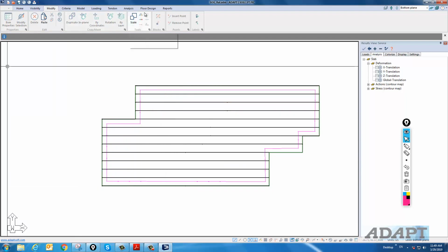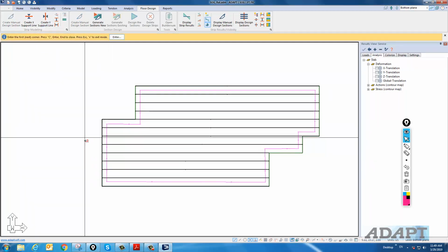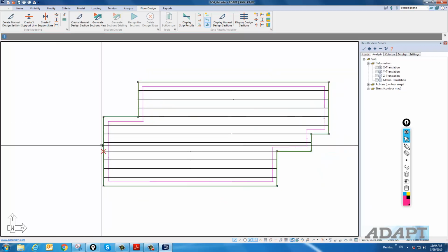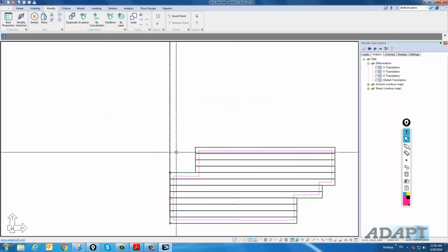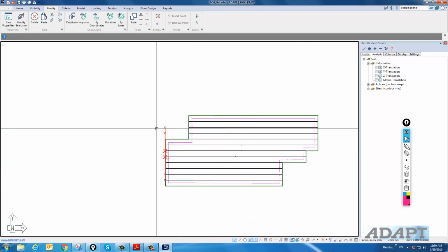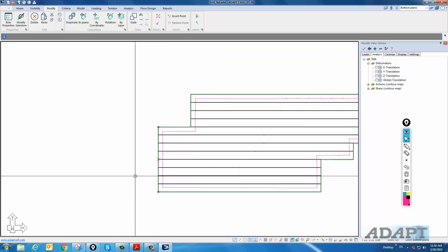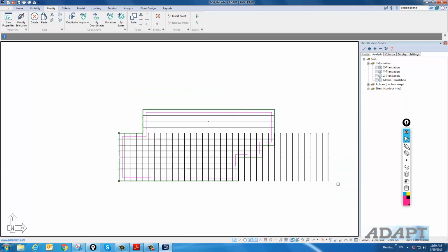Now I'll do the Y support lines. So back under floor design, I'll create this support line, and I'm going to copy that support line. This will be every 5 feet. Here we'll say 35 copies. And you'll notice I copied that in the wrong direction. So we'll delete that. Should have been in the positive. Try that again, in this direction. 5 feet in the X direction, positive. That's following this global convention for the X and Y axes. And then we'll say this is 35. Okay, we'll delete out those we don't need.